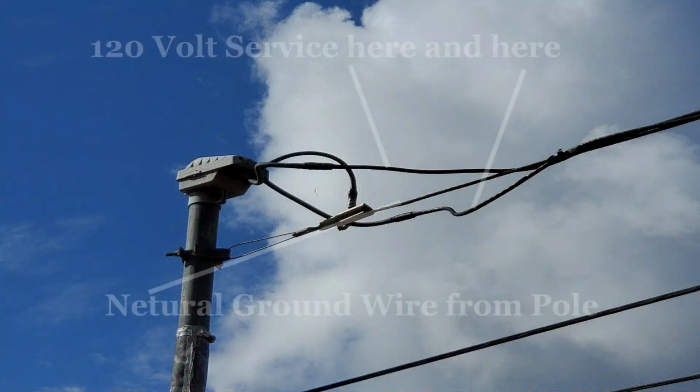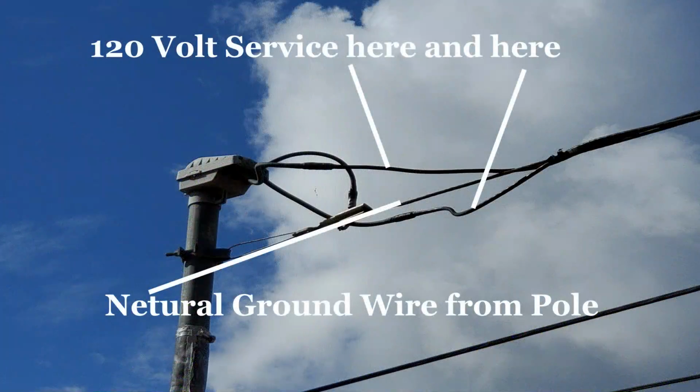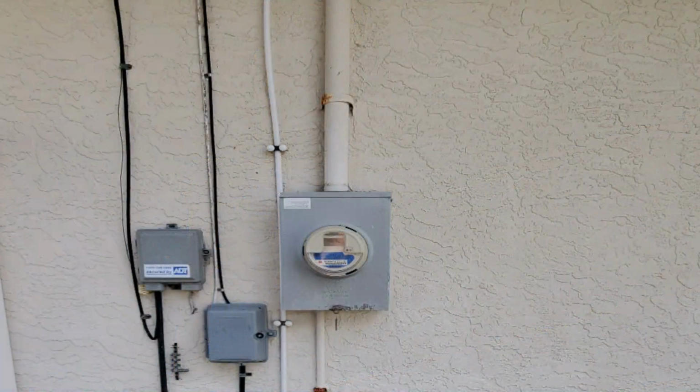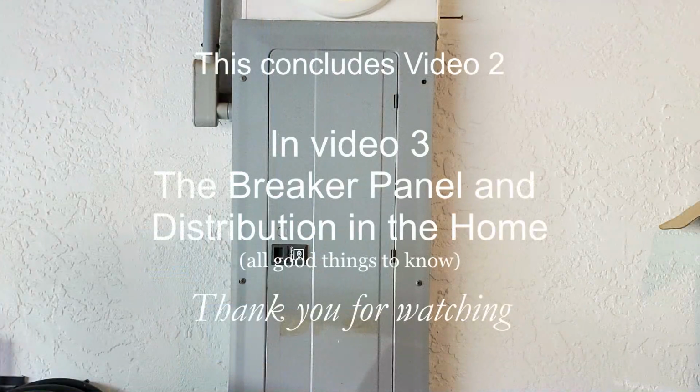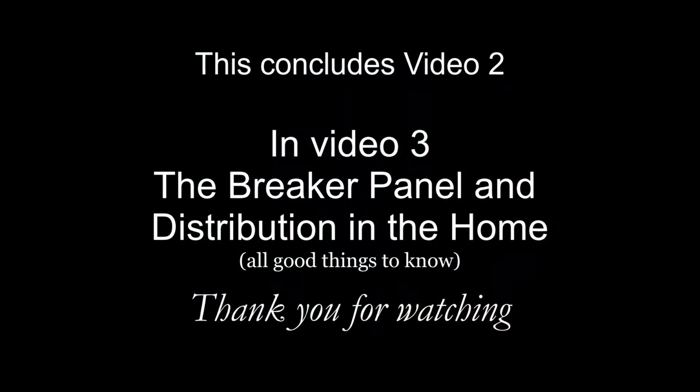The service lines are attached to a receiving house mount and are routed through a conduit to the electrical meter. From the electrical meter, the lines are terminated in the house electrical distribution panel. We'll have more about that in the next video. This concludes video 2. In video 3, we'll cover the breaker panel and distribution in the home.